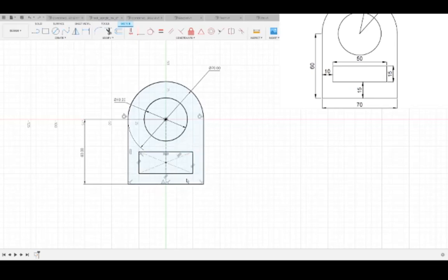So now we have that, and we have our own set of defining dimensions here, such that we know the rectangle is 15 by 50 millimeters, as seen in the drawing. So we can go from that to that. That's already set to 50, so we can hit enter, move on to the 20 millimeters, and we can make that 15, because it snaps to grid, so that's why it's not like that. Oh, what in the world? Something went wrong on my screen. I think that might have been Fusion. Anywho, that's said and done.